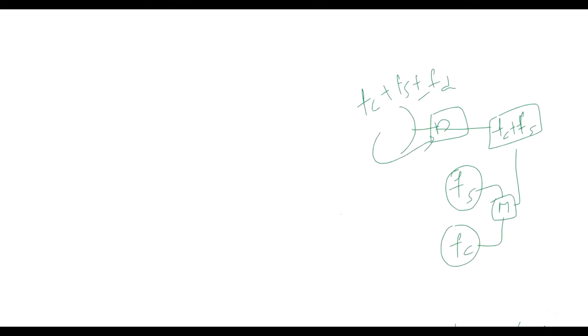This diagram, the MTI radar. It is a combination of both pulse and Doppler effect to improve the performance and the measurement capabilities. This radar system is specially used for which one? It is specially used for moving target objects. MTI full form is moving target indication radar. It is specially used for moving targets. The targets are moving from one place to another, which means the targets are not stationary, not fixed at one place.